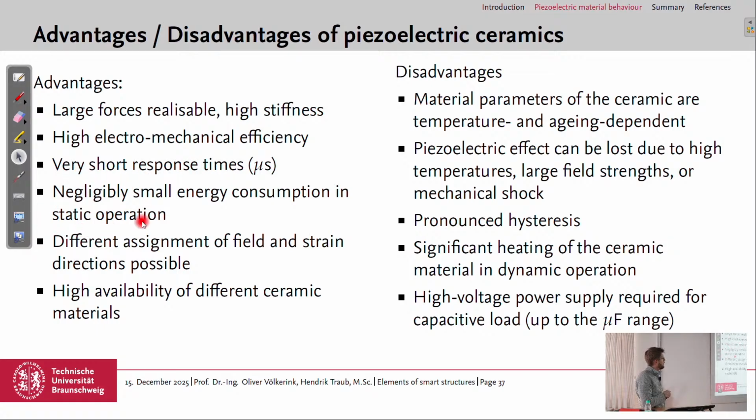In static operations, we have very small energy consumption. We can assign different field and strain directions, so we can use the D33 and also the D13 effect. And we have high commercial availability of different ceramic materials.